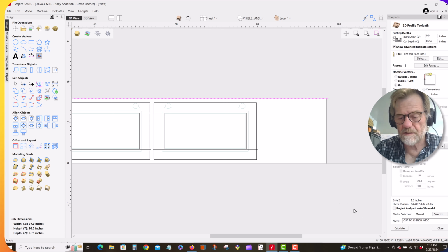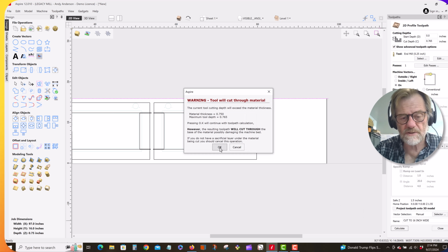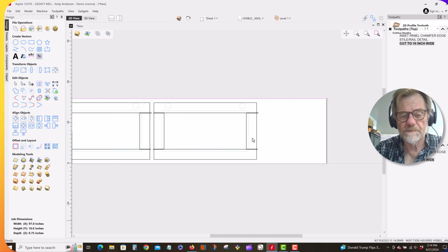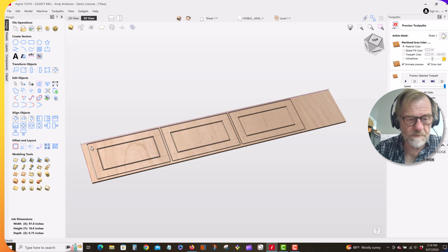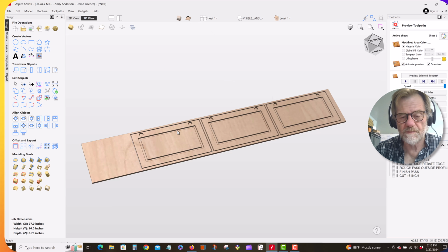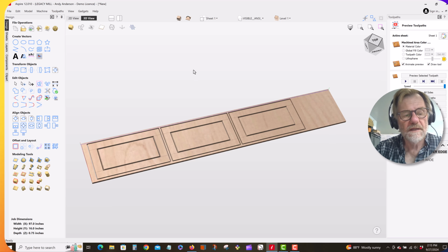So this is going to cut the first 16 inches out of my 4x8 sheet, and that will allow me to grab this end and flip it end for end so we can do the second side, which of course has this side here. I won't have to try and switch the long 4x8 sheet. I work alone, so being able to flip a 16 inch wide 8 foot long piece is easy. Trying to flip a whole 4x8 sheet, that's too much like work. We don't want to do that. So I've added that step to this, and now these are ready to go out, take out to the machine and get to work.